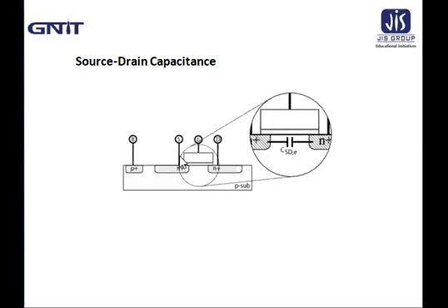The value of this capacitance is difficult to calculate because it is highly dependent upon the source and drain geometries. For longer channel devices, CSD is very small in comparison with other extrinsic capacitances, and that is why this capacitance is normally ignored.